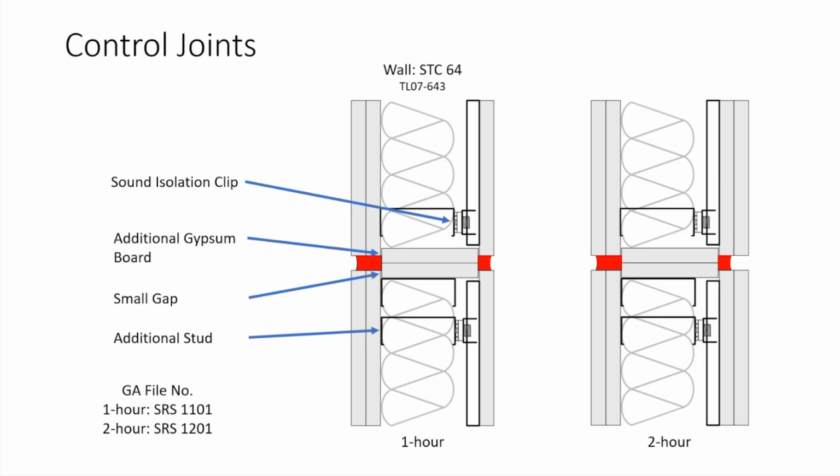This is acoustic, so we also want acoustical sealant that's fire rated. Acoustical sealant stays flexible, so it doesn't open up gaps over time as it dries and cures and shrinks. And in this case, we also want to make sure that the drywall that's held against the stud is held off just a little bit from the drywall on the face of the wall, so we don't get a structural transmission path through there. See, I said they're going to always show up in both of them. And this is kind of the basic gist of this. You can do this with wood studs as well. You're just continuing that mass layer, and in this case, you're making it more circuitous there.